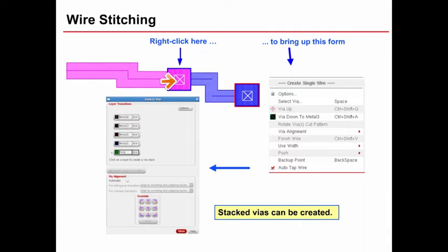So when you left click, there it is, and then you move away in metal 1, and then whenever you're ready to go back up or go from metal 1 to anywhere else, you could right click and choose another one to move to. And then you could also take a look at the alignment if you wanted to offset it.